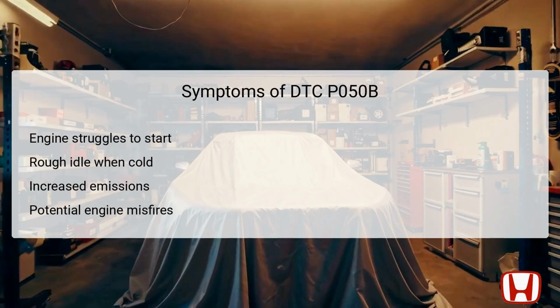Increased emissions may also be observed, as an inefficient combustion process due to incorrect timing can lead to unburned fuel being expelled, resulting in higher levels of pollutants. Lastly, potential engine misfires can occur if the ignition timing is consistently incorrect, creating performance issues and possibly damaging the engine over time. Awareness of these symptoms can aid in early diagnosis and resolution of the underlying issues.